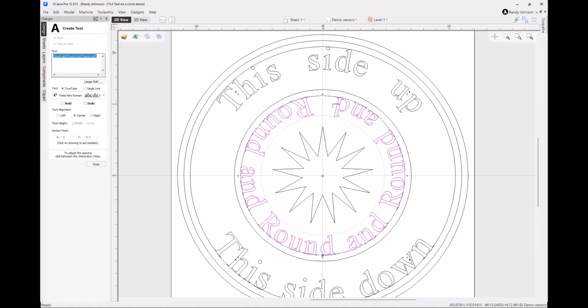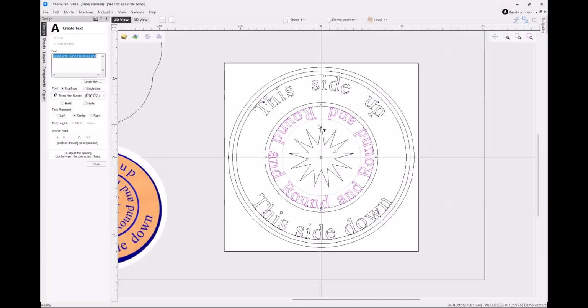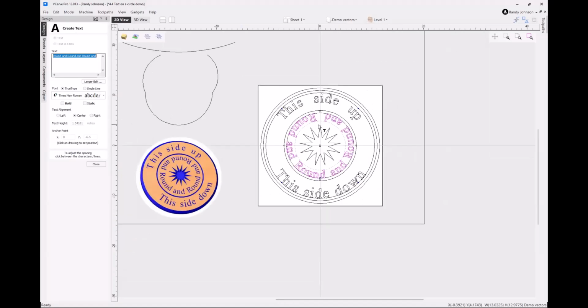Notice the tool doesn't come up. So in this situation, to control this spacing, I have to add or delete space between the letters, and that then compresses this end space a little bit. So the text on a curve is quite powerful.